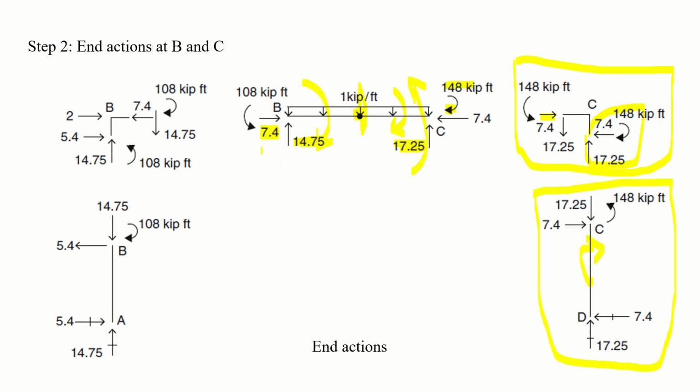Okay, and I think I just made a little bit of confusion over here. Let me clarify it to you. And that confusion is that I told you that 148 plus 128 is 256. Actually, it is 276. Okay, I just realized that I just mispronounced. 148 plus bending moment due to this UDL is 128. So 148 plus 128 is equal to 276, and the reaction is 17.25 into 16, and that is also 276. So these cancel out each other.